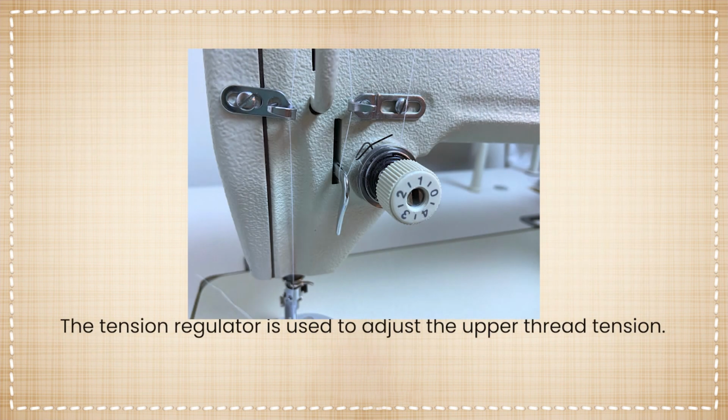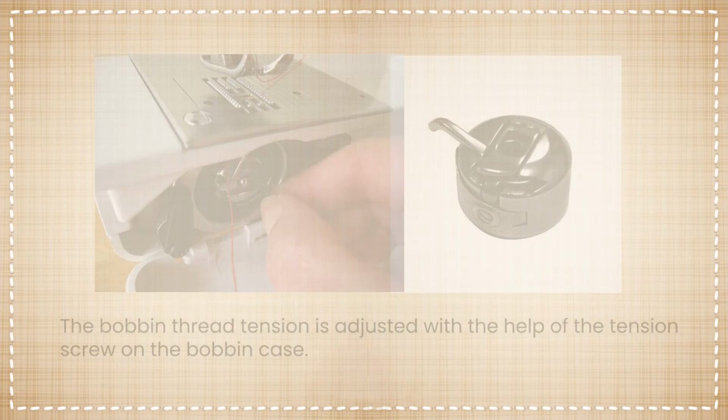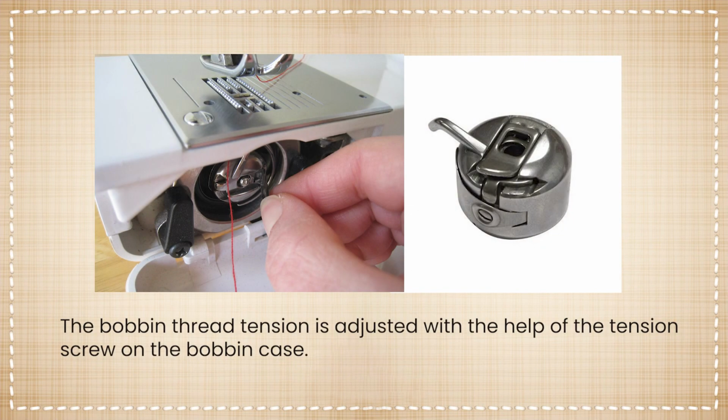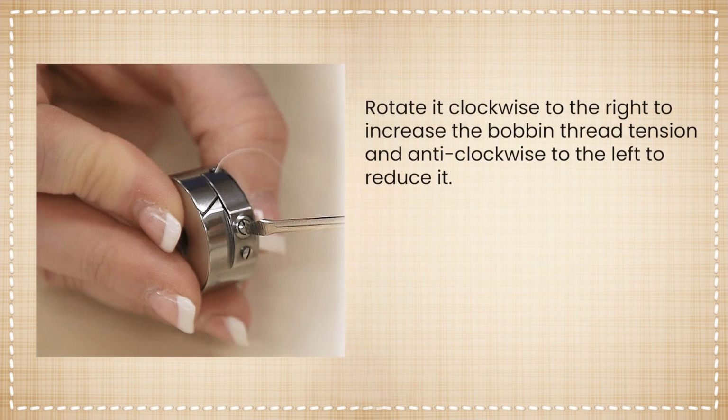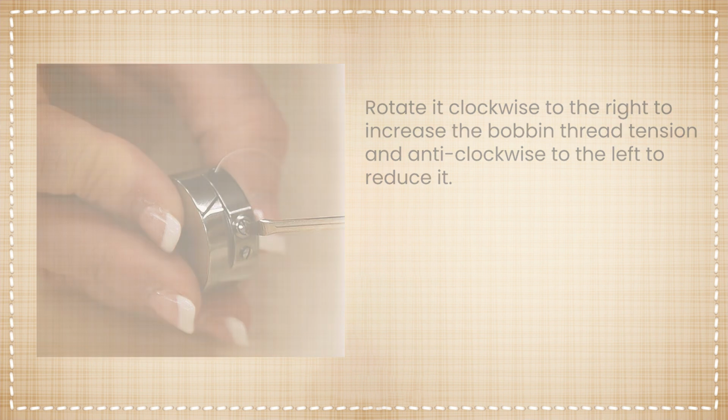The tension regulator is used to adjust the upper thread tension, while the bobbin thread tension is adjusted with the help of the tension screw on the bobbin case. So you need to rotate it clockwise to the right to increase the bobbin thread tension and anti-clockwise to the left to reduce the tension.